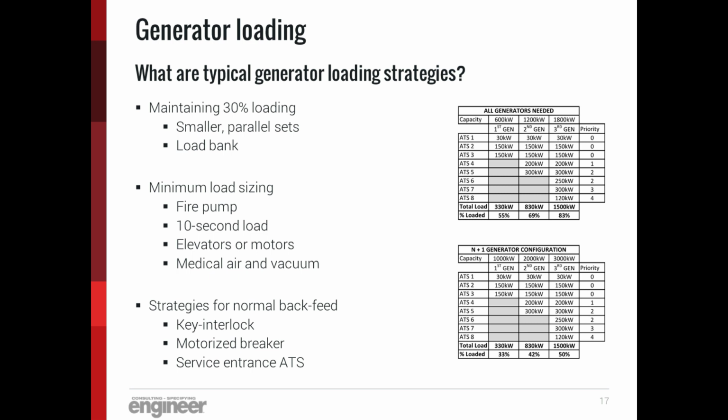Now, when we're loading, you've heard the term 30% minimum, right? That's going to be a manufacturer's requirement to prevent wet stacking during testing. And that's something that, as David mentioned, NFPA 110 says comply with manufacturer's testing. So we look at, are we getting enough load? And we'll talk about load banks on a slide here.